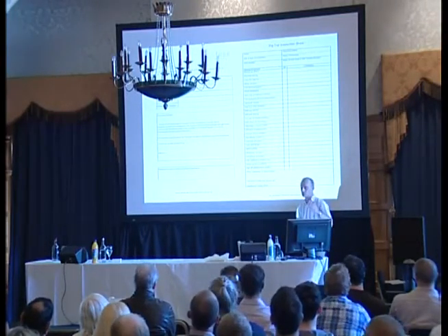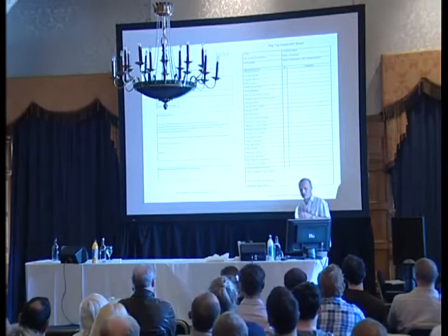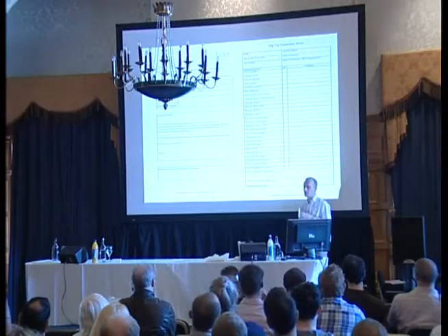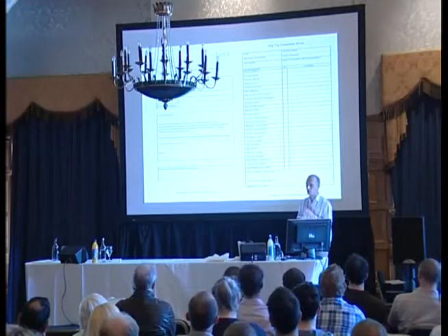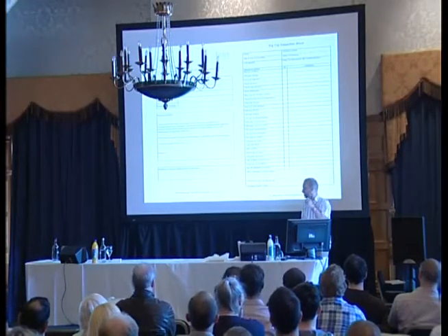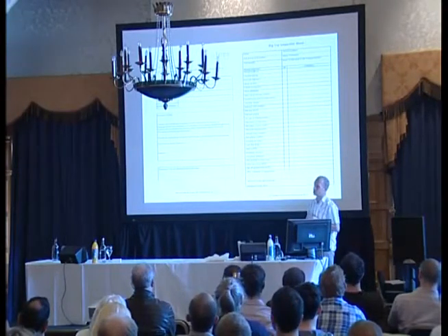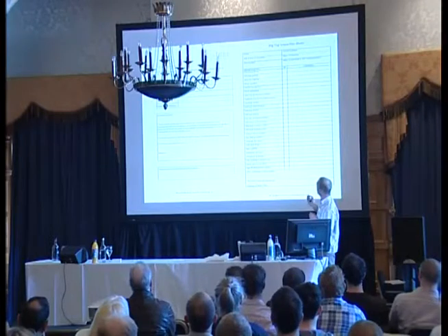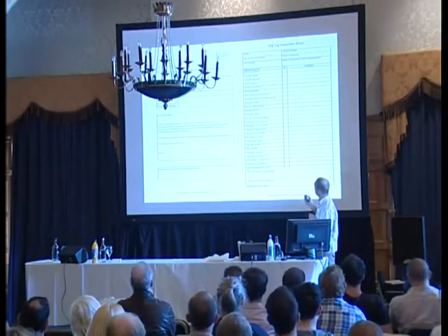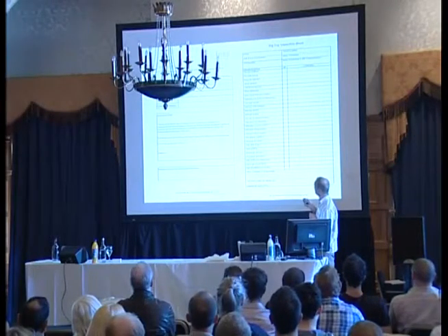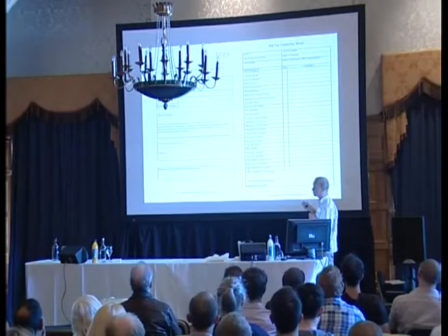Obviously, going back to our wooden house that I showed you, our two-tier bar, that's a little more tricky. But somebody will have come up with some plans at some point, because they'll have had to cut the wood, they'll have had to design it, work it out. There should be drawings for that structure, and you are asking them to sign off against that structure. On this side, what I was talking about, the big top inspection sheet, so what are we looking at? King poles are pinned, king poles are aligned, loader certs for the winches, main guide tensions, main guide pinning.